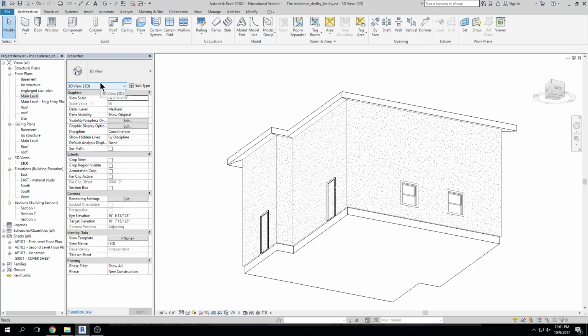Detach, another roof. Yeah. Okay, so you detached it, now you want to attach it, is that what you're doing? Well, I just wanted to go down to the top of the level. That's what I thought it was complete. Well, so what you did though, so the top constraint is top of wall, which is where it's at. Yeah. Oh, it's an interior wall. That's what you were. Yeah. Why did I look at that? Because you accidentally picked that instead of an exterior wall, and you attached it.